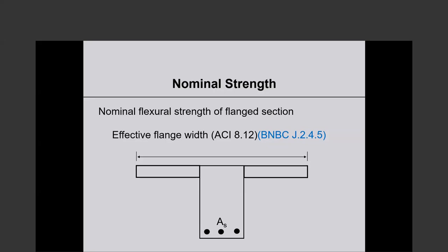Okay, so when you apply loads on this beam, the part of the slab on both sides act like flanges of that beam. Those also bend, just as the top portions of the beam go into compression.